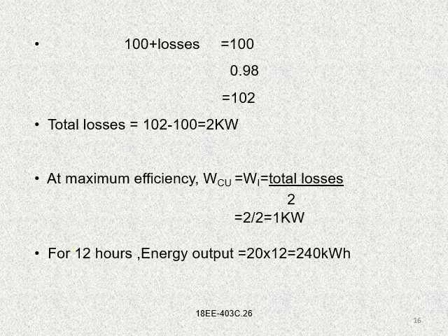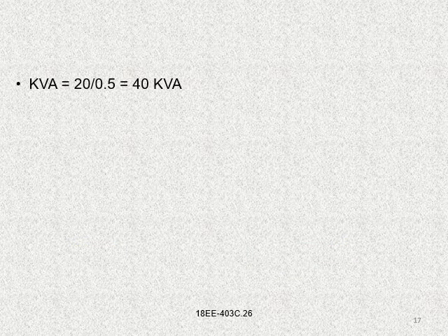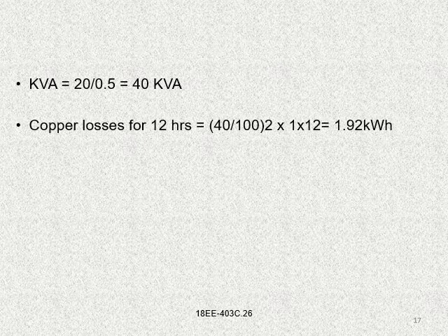And for 12 hours of duration, the energy output is 20 into 12, which is 240 kWh. The kVA is equal to 20 by 0.5, which is 40 kVA.